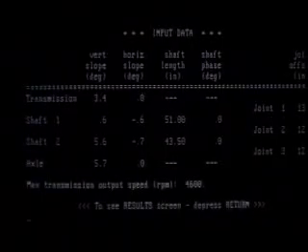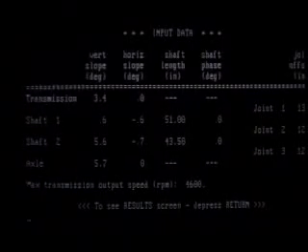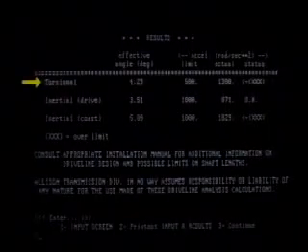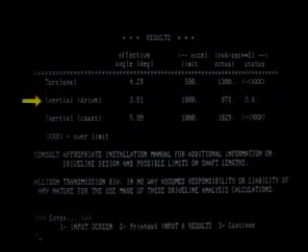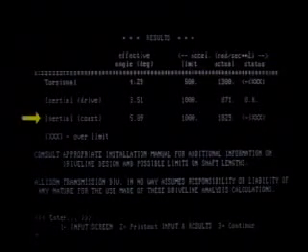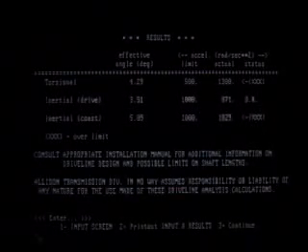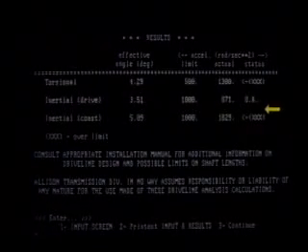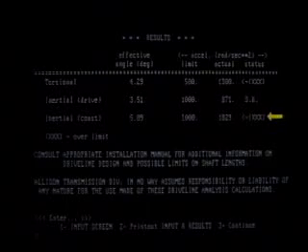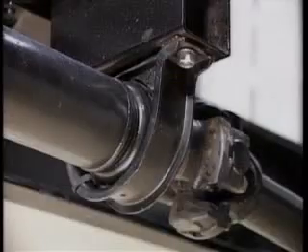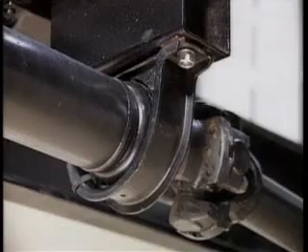When finished, the software summarizes your inputs and calculates results. These results include torsional acceleration, drive U-joint inertial acceleration, and coast U-joint inertial acceleration. Each acceleration is labeled either OK for acceptable or XXX for unacceptable. To better understand the software's calculations, let's take a closer look at what these terms mean.